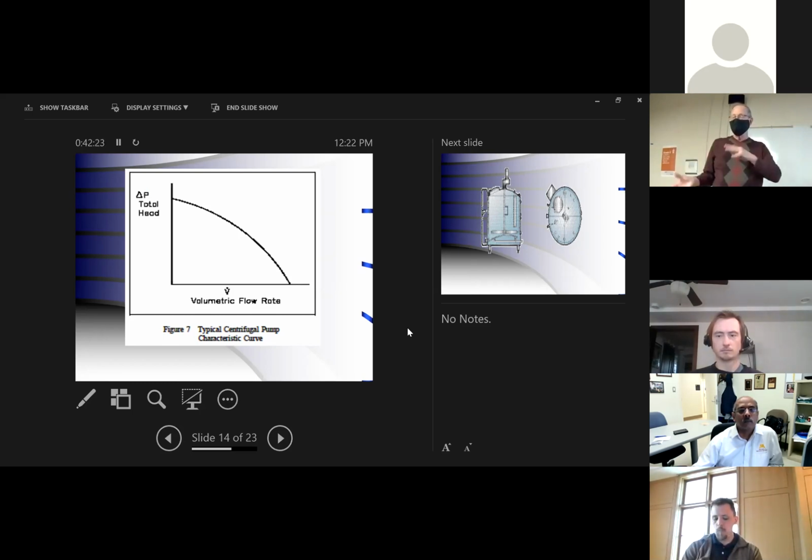That's the thing you get here with the centrifugal. You have this variable amount of liquid that can be moved depending on how far you're pumping it, how high you're pumping it, and so forth. But in most plants where you can live with some variability, and you aren't worried about all this timing to the last millimeter, so to speak, or milliliter of liquid coming out, you should be fine with centrifugals. And again, a lot cheaper to buy.